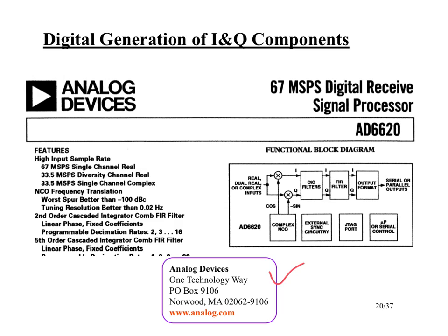But basically, if you look at this structure, this looks exactly like what we just saw. The only difference is that for the discrete-time version of this, we don't really need a phase shifter. We can numerically generate cosine and negative sine. We can do multiplication, obviously digitally, and then we've got our low-pass filters, and they use a particular type of filter called a CIC filter, together with an FIR filter.